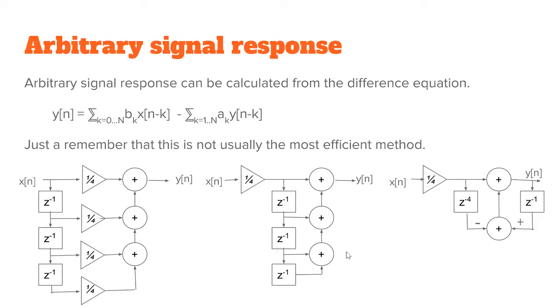The same way, on this linear time invariant system, there are different methods to optimize the calculations. For example, if we have a symmetric impulse response for FIR, then we can actually calculate the multiplication before adding. So it halves the amount of multiplications.